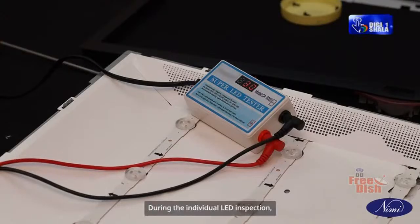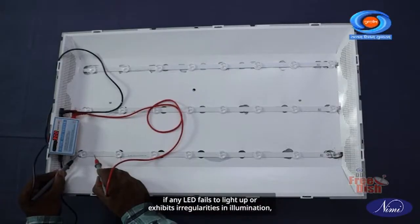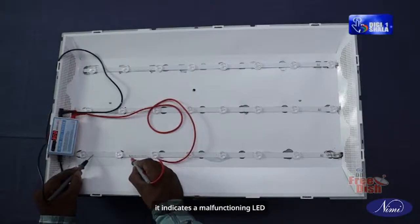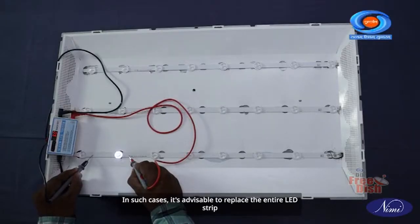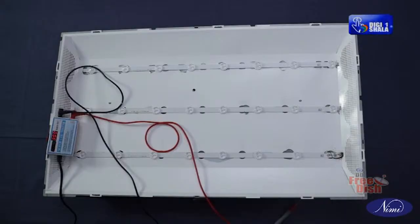During the individual LED inspection, if any LED fails to light up or exhibits irregularities in illumination, it indicates a malfunctioning LED that requires replacement. In such cases, it is advisable to replace the entire LED strip rather than attempting to replace individual LEDs.